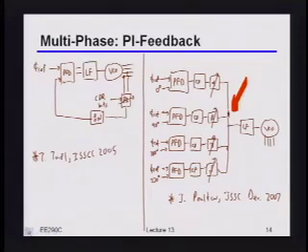So if you compare the two of them, I guess a good trade-off is the first one, because it's a pretty reasonable thing to do. You have to work out exactly what context you're in, how much multiplication you need, and what the reference is. But this is indeed a fairly reasonable approach as well, and people are using these kinds of things. Although it's heavily dependent upon how much multiplexing you're doing in the first place. If you're not doing very heavy multiplexing, for example with a full rate system, then there's no difference between doing this and just having the phase interpolator open loop to begin with.